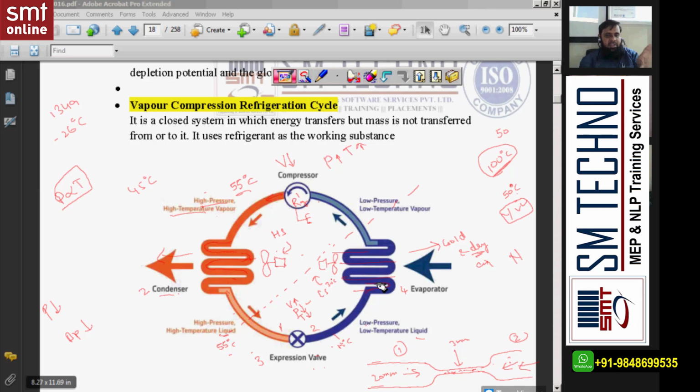And the refrigerant, listen, is at low pressure, so it can boil at low temperature. So when the room air heat is given to the refrigerant, the refrigerant starts boiling at low temperature. And when it is boiling, it extracts more and more heat. And when it comes out from the evaporator, it is low pressure, low temperature vapor, a change of phase. In the condenser, vapor to liquid. In the evaporator, liquid to vapor by extracting the heat. Extracting the heat means it will cool the air. And again the low pressure, low temperature vapor is sucked by the compressor, and the cycle continues, right?